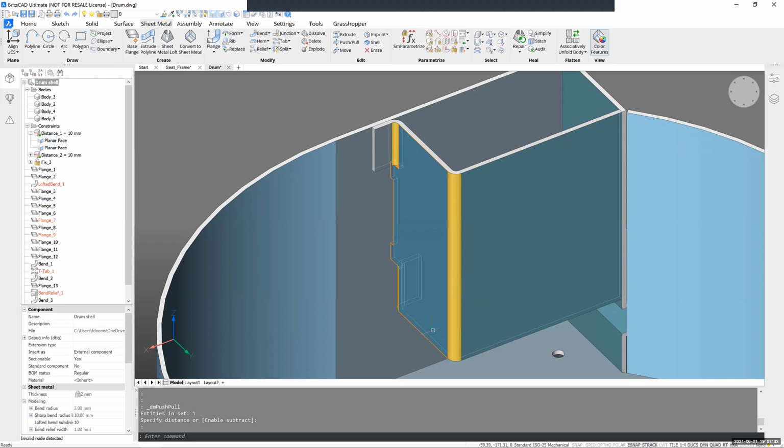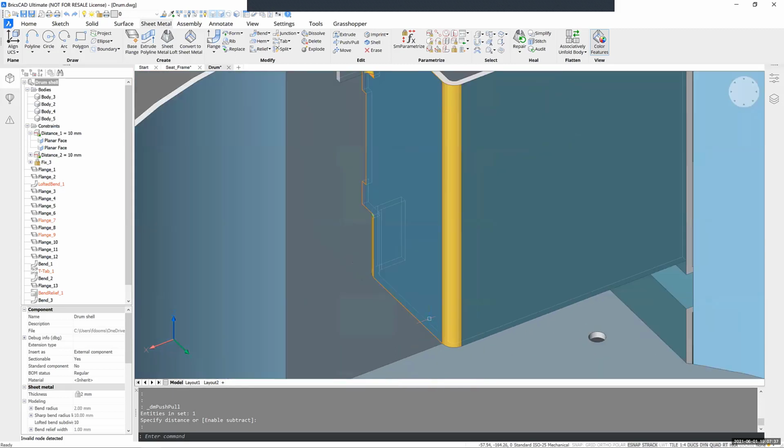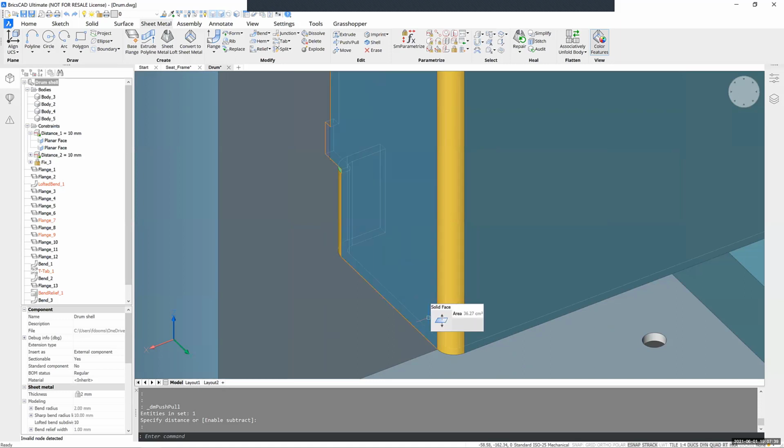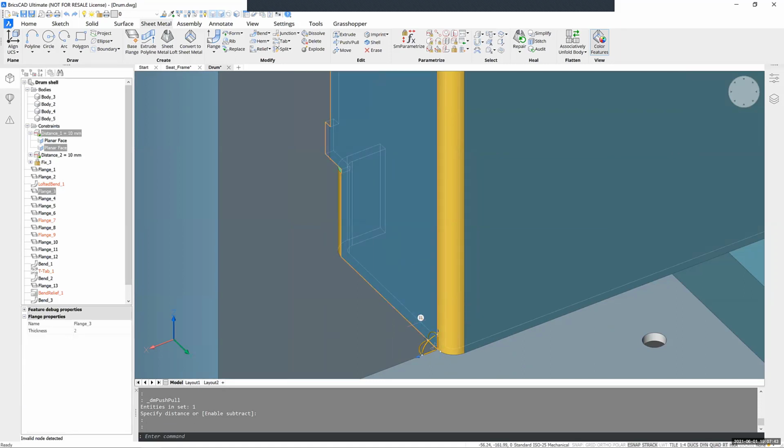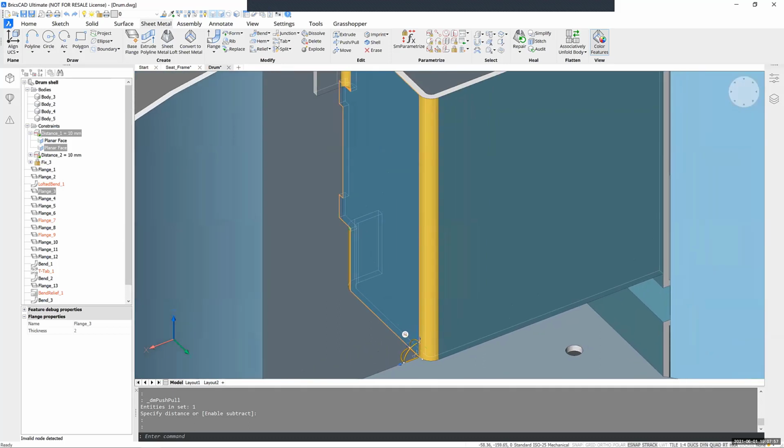And then you can long click here in the bottom right corner. If you click in the bottom right corner, the manipulator will appear at the right location right away. So you just long click and it will appear here. If it would not appear on the correct location, you can always move it with these little white grip points, and you can move it and snap it to any snap location that you have in your drawing.